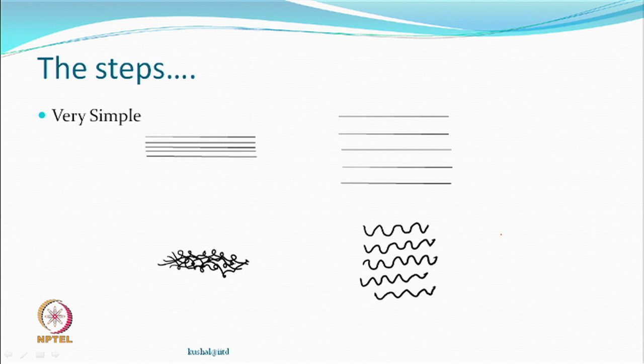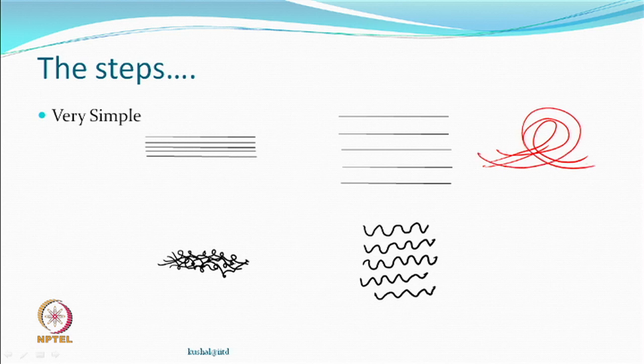So, this opening, why is it important? If you do not open, then you may actually land up with a bundle of filaments making, let us say, one loop here. So, this bundle will get some force and it starts bending. If all of them bend together, it is a bad idea. They will open without making any effort almost. So, what we are interested in is that each filament must behave individually to the input of the compressed air, and they do not have to follow anyone. Based on their position in the jet, they should interact and form bends, create loops.